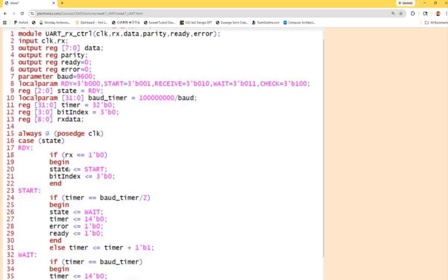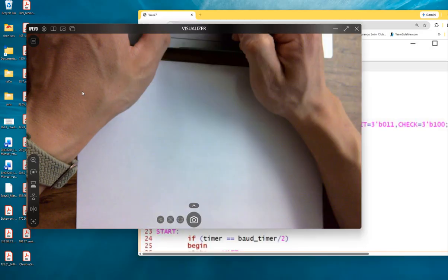Maybe, but the thing is, the clock can run really fast. If there's only a little difference or error just because of the period of the clock, it probably doesn't matter that much, right? Because the clock is running really fast at 100 megahertz, so you can consider that it's almost synchronized to whatever the signal is that you need. It's so fast, right?